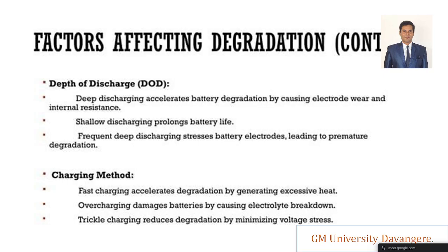Shallow discharge I also explained very clearly: a 20 to 50% depth of discharge prolongs the battery life, so there is less stress on the electrodes. Shallow discharge makes for a prolonged battery life. At least come back to less than 50%, 40%, 30%, 20%, then go for the charging point. Don't go immediately when it is at 70 or 80%.